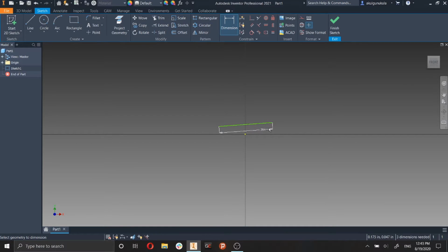So now if we want to edit it another way, I'll show you how that is done. Let's say that you didn't have the dimension tool selected. Then you would just go over to the measurement and then hover over it, double click it, and now you'll be in the same edit dimension dialog box. And here I'm going to show you how you can make an equation, for instance. Let's say you want an equation like 2 times 3 minus 5, for instance. It would solve it out and give you the final answer in whatever units specified, if there were units. The cool thing is that when you do the equation, it keeps it in there, so you know where you got that number from. So this is a useful tool.